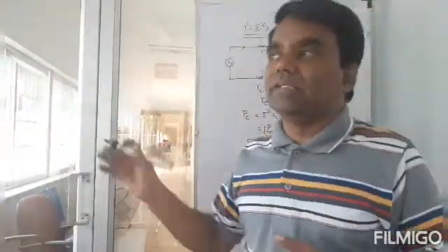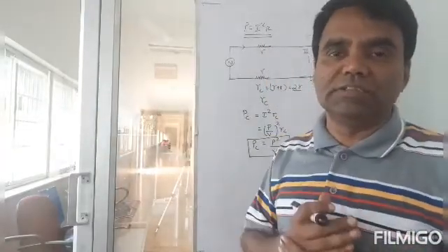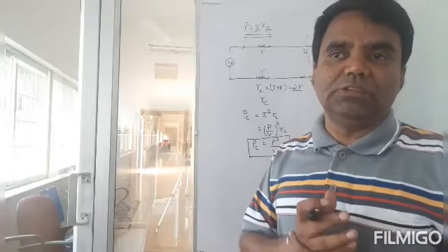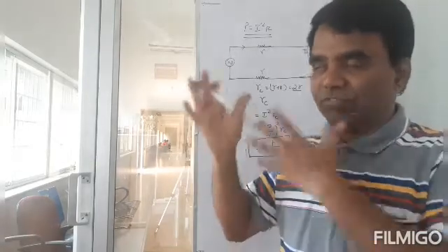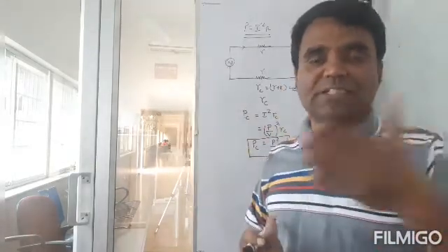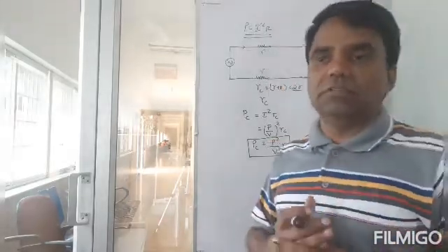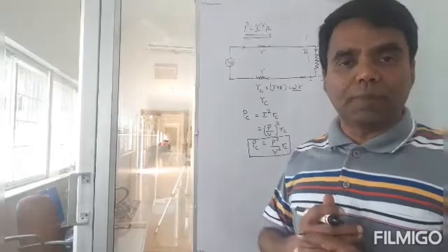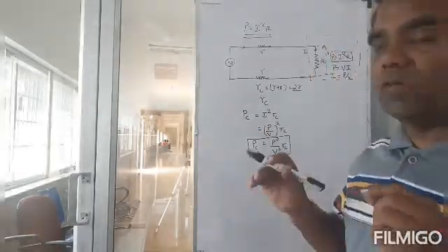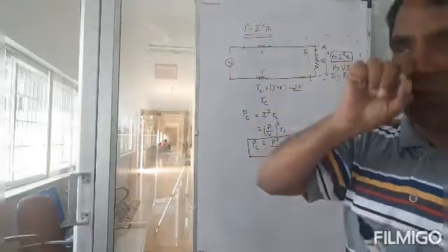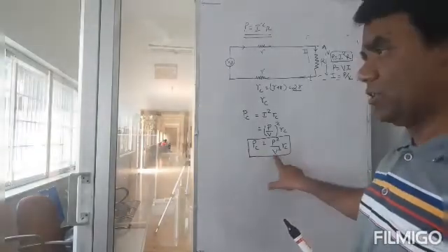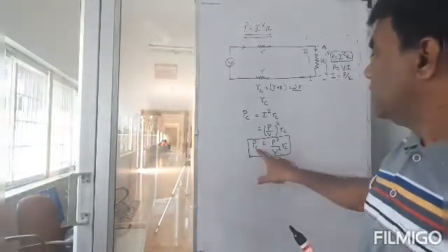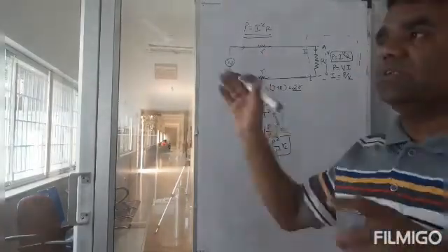And that is why when they transmit power from A to your house, they will have transformers and stuff, 220 kV and 11 kV transformers, 22 kV transformers, 110 kV transformers. You can find them, different types of transformers. We'll study about transformers later when we study alternating current. But understand that it is always useful to transmit power over long distance at a higher voltage. That reduces the amount of loss you will suffer in transmission.